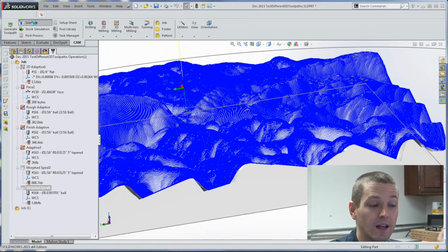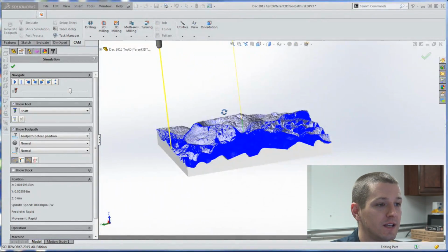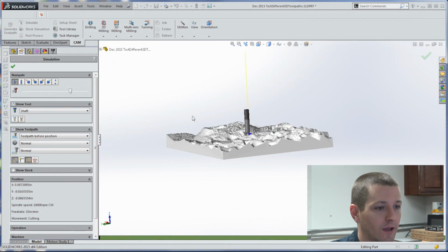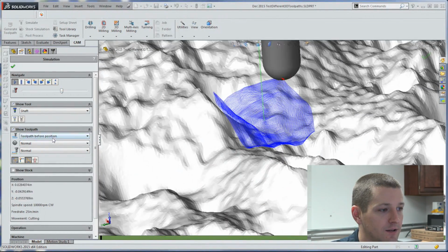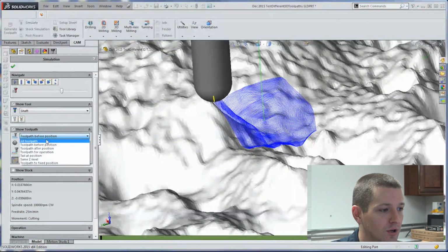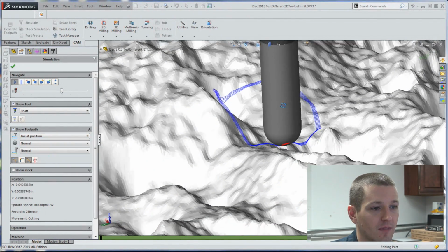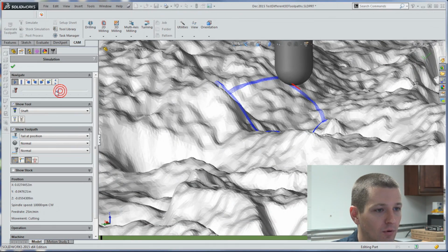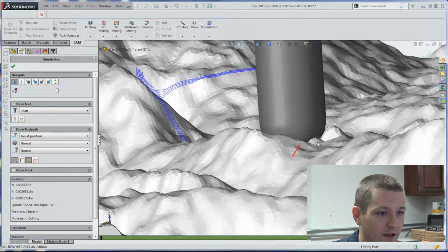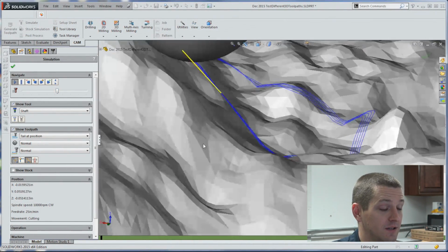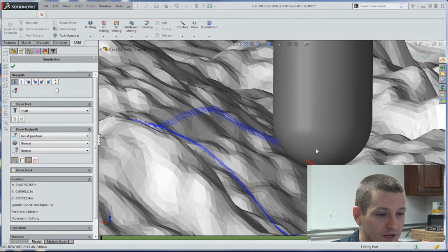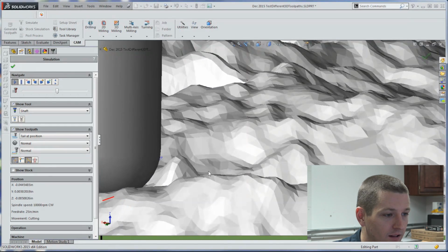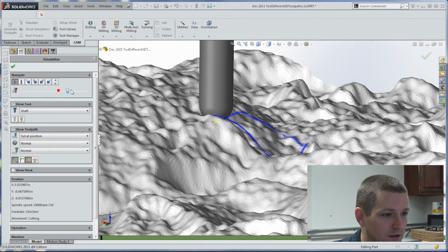And what's cool is we can use stock simulation as a really helpful tool, but let's look at just the regular simulation, and hopefully it'll work okay here with the graphics card. So I'll slow it down, and let's change the toolpath to just show a tail. And if you slow it down a little more, you can really see, as we zoom in, I mean, it's crazy. You can just watch it going over, and you can see just how fine a detail this part is.